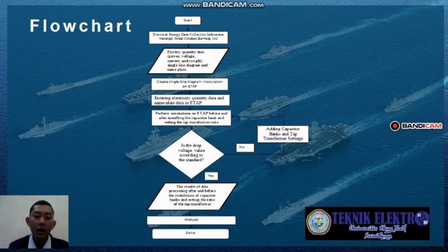Then perform simulation in ETAP again. But if it is according to the standard, the analysis result of the data processing after and before the installation of the capacitor bank and setting the ratio of the tap transformer is taken. If the analysis has been done, then finish.